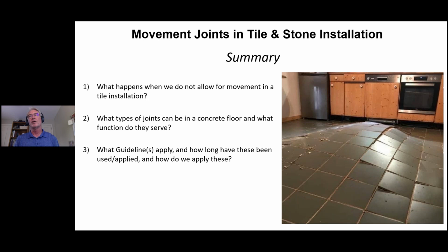We see this all the time, right, Jim? Yeah, it comes up all the time. So it's a great question. Let me explain my preference. My preference is to have sealant in there first and then come back and grout to it. And that means it's got to set up and cure. A lot of people don't have the patience for that. And so they'll go in and grout.